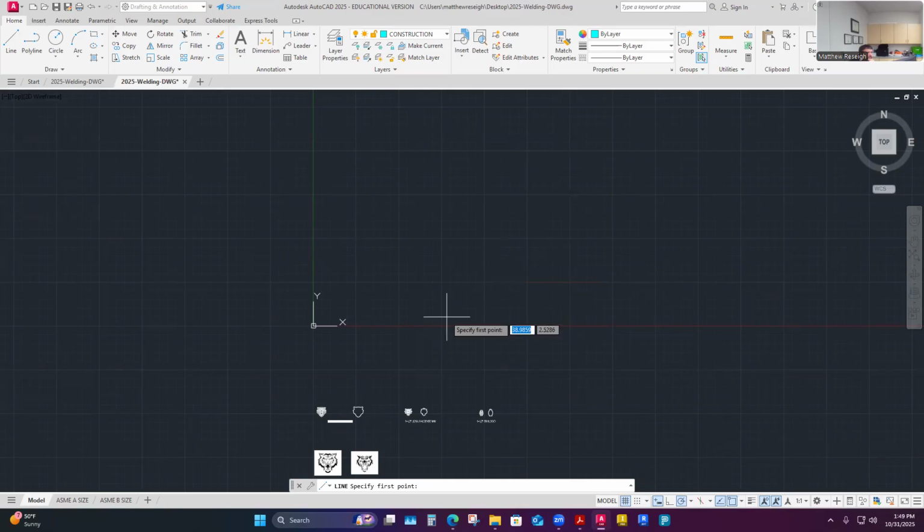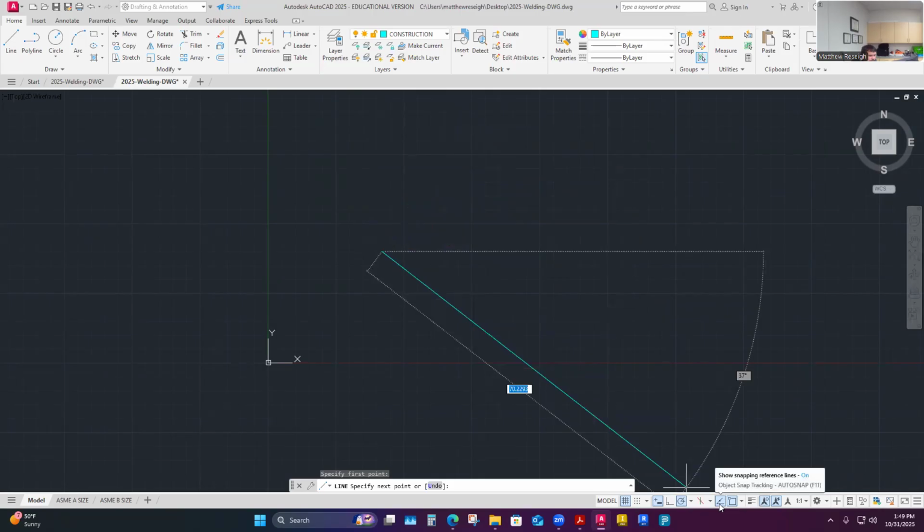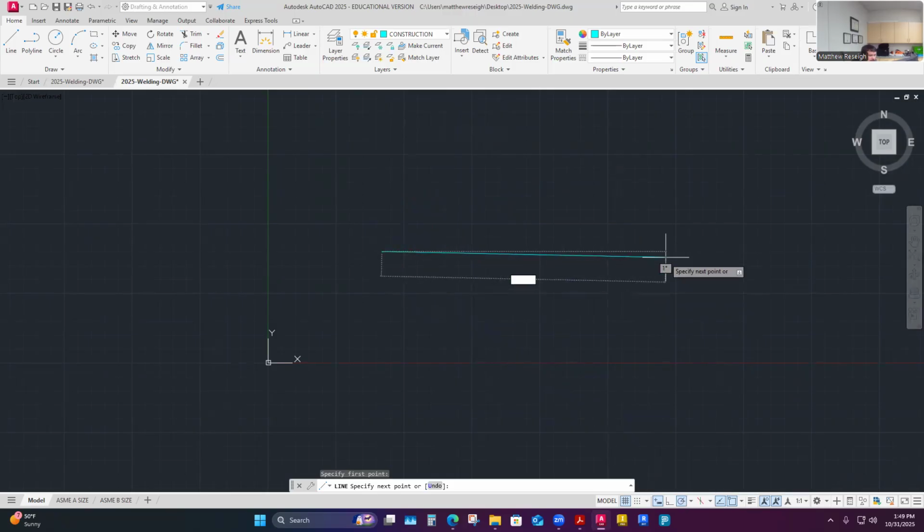So if you were going to build a rectangle by line, 11.5 by 18, here's one way you could do it. Maybe I'll start at the bottom. It's 18 wide by 11.5 tall, which is the boundary of our part. So if I just left click here, then I'm going to start drawing. I use this polar snap tracking right here to display those. I have that on so it displays these green projections when I hit those specific degree increments,